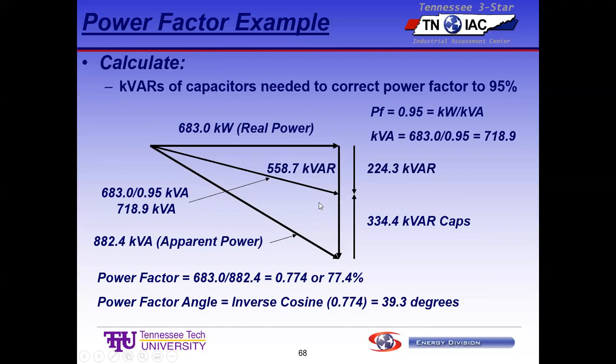So if this kVAR goes down, you can drive this thing past 1, and oh yes, they'll penalize you for leading power factor as well as lagging, not as much. Even though it helps them, they will still penalize you for it. I've seen bills where they get penalized for leading and lagging in the same month. Oh, it's a dollar game out there in the big world.